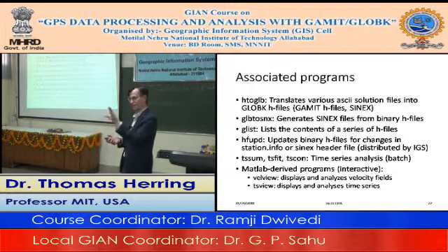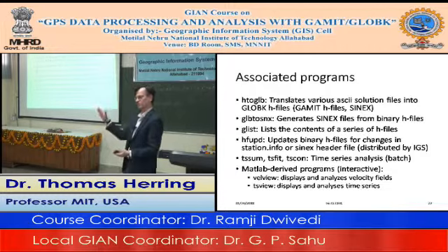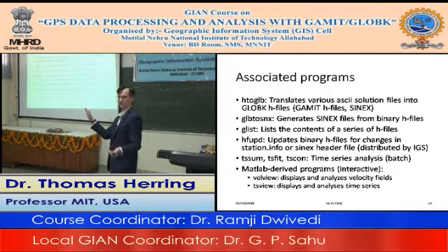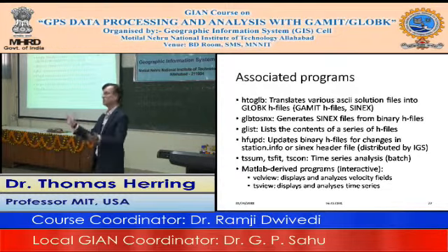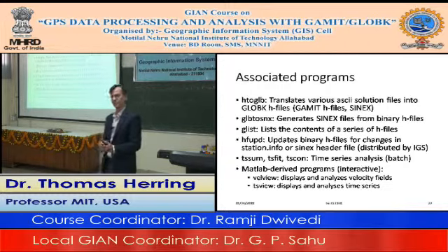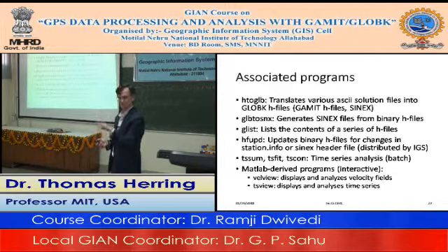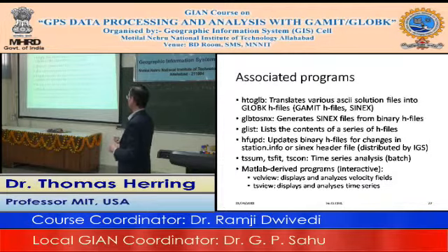So if someone sends you time series in ITRF 2008 and you want to rotate those time series into the Indian reference frame, you can use TSCon to rotate the time series and generate time series in a new reference frame. Again, using a set of stabilization sites and a set of a priori coordinates, exactly the same commands and formats that you'd use in GLOBK work in TSCon.